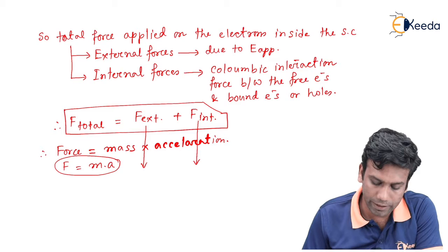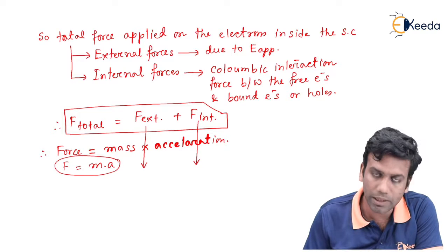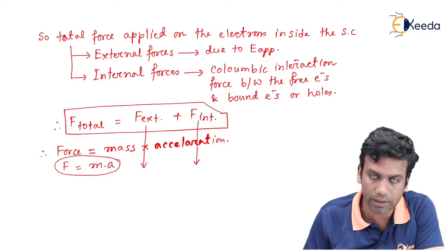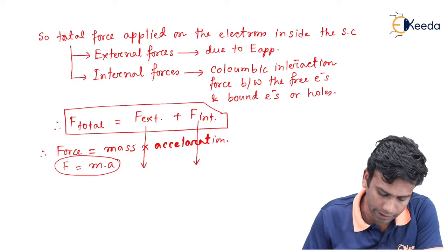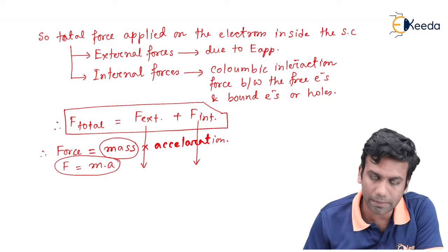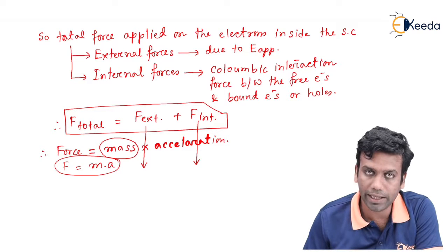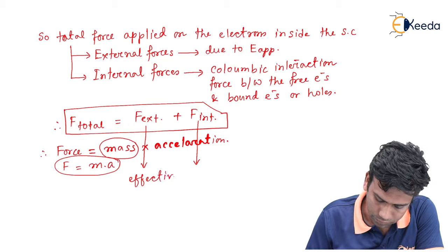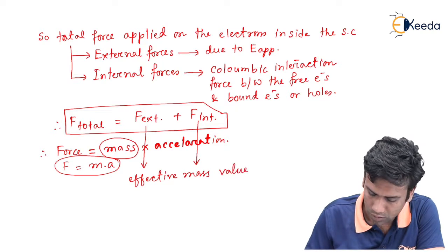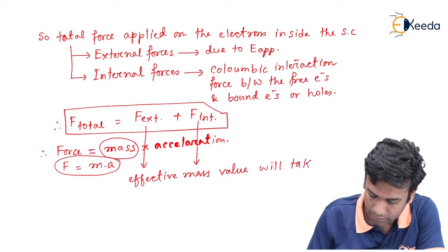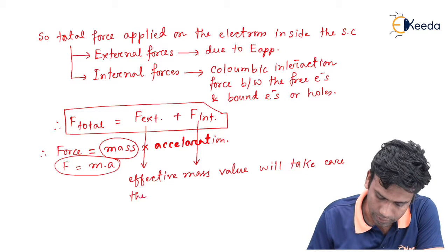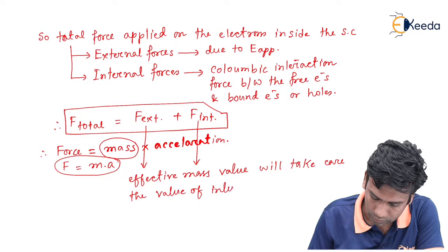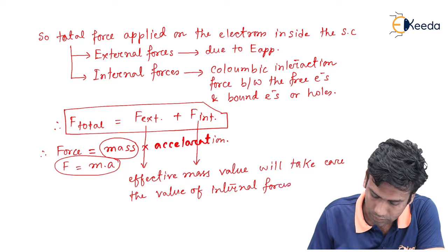To incorporate the information that there are internal forces inside the semiconductor along with the external forces, we will change the mass of the carriers and say they have some effective mass, and this effective mass will take care of the internal forces inside the semiconductor.